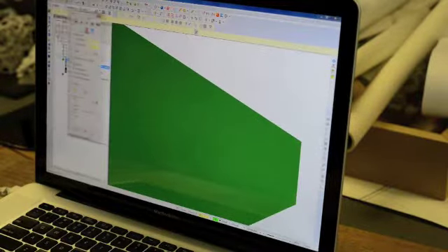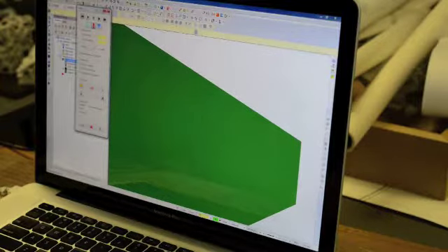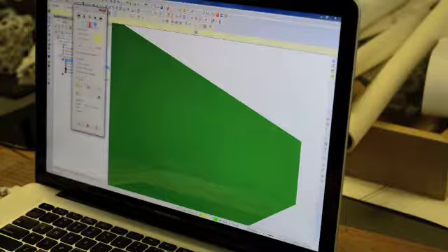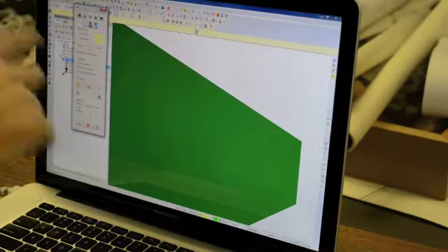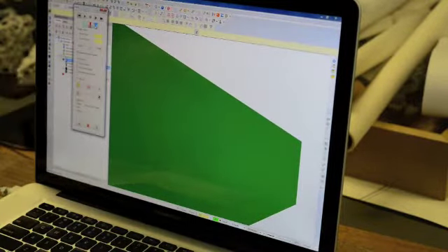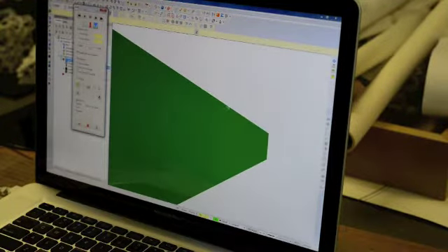And they give you a few different options for how you verify what you're doing. So over here, this little tornado swirl is like turbo, so it'll do it in like 2 seconds. But then these other two give you a little more control over how quickly it generates the preview. And I like to choose this one over on the right because it shows the tool holder as well. So it just helps you understand even better what exactly you're doing, and if there were conflicts, you'll be able